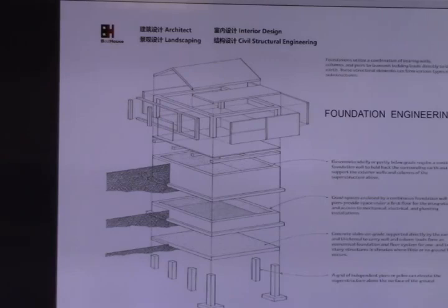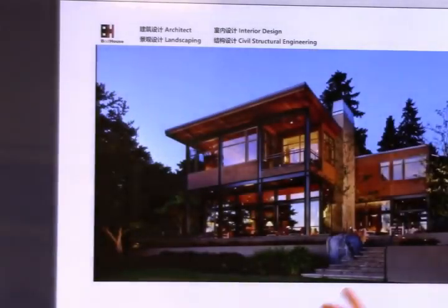And the steel you just use for bigger spans, you should not cover with wood beams. Yeah, I understand. You don't put the floors with concrete, you don't put the ceiling with concrete in the residential. You don't need it. Some areas are necessary; we shall use steel and concrete, but for the main building we only use wood framing.